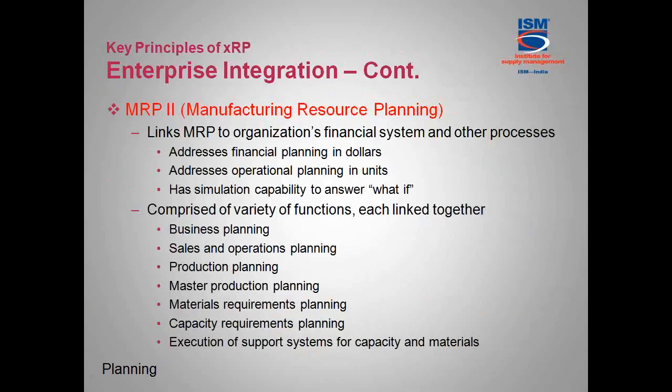And against that we are making the possibility that all resources should be available. Now the next level plan is the master production schedule. The master production schedule is talking about which particular product we want to make. At the production plan we are talking about how much we want to make. Here we are talking about which one we want to make. So the master production schedule is the mix level plan, not a volume level plan, and at this level we are talking about the availability of all critical resources.